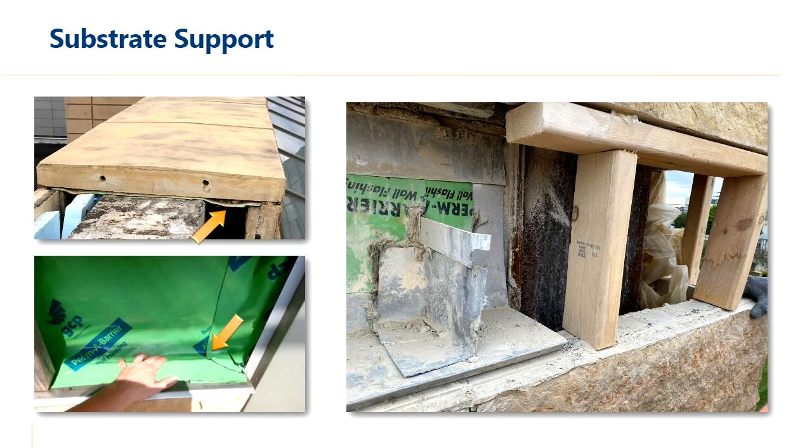We also found instances where the flashing didn't have adequate support, and so over time it was starting to sag. With flexible membrane flashings, you really only want to have them span about a half inch unsupported. Otherwise, they will want to droop and sag, and those joints and side laps will want to pull apart from each other, leading to water getting in.